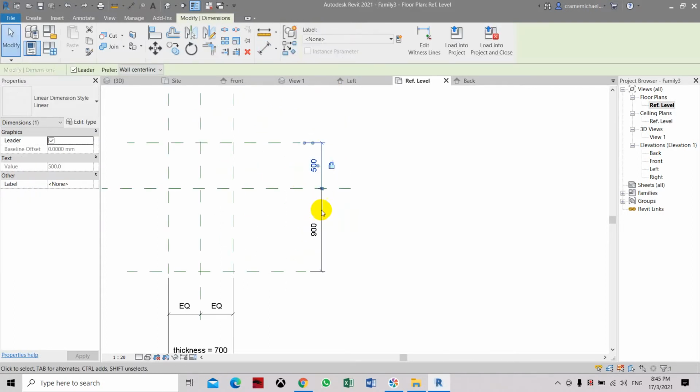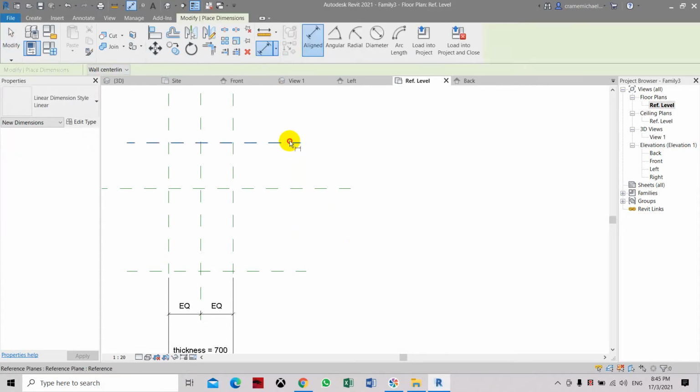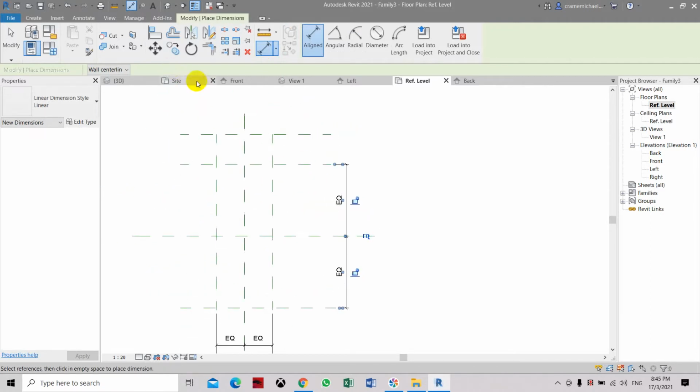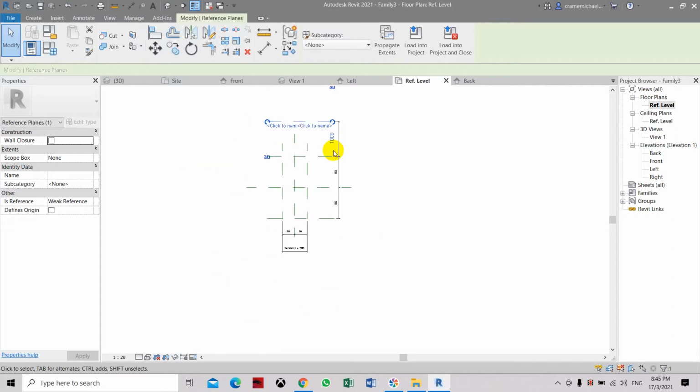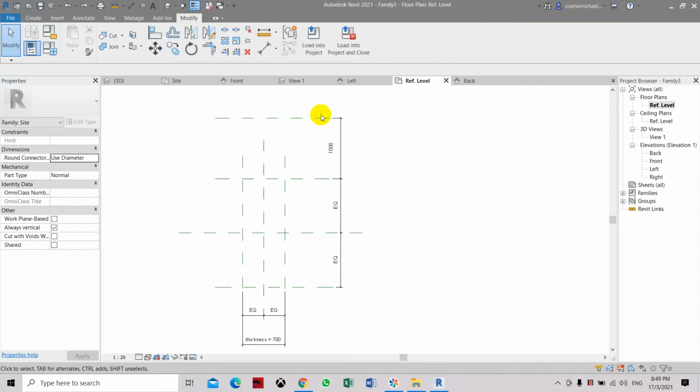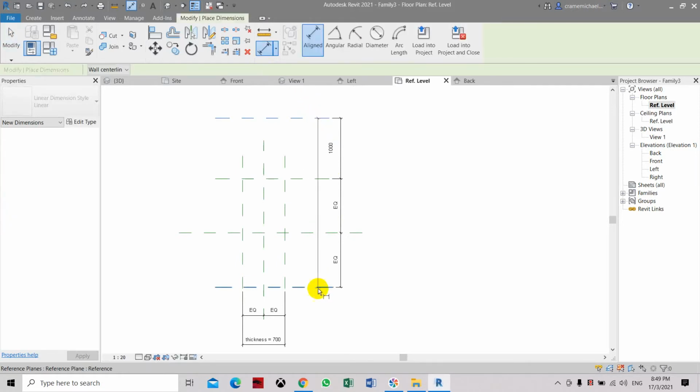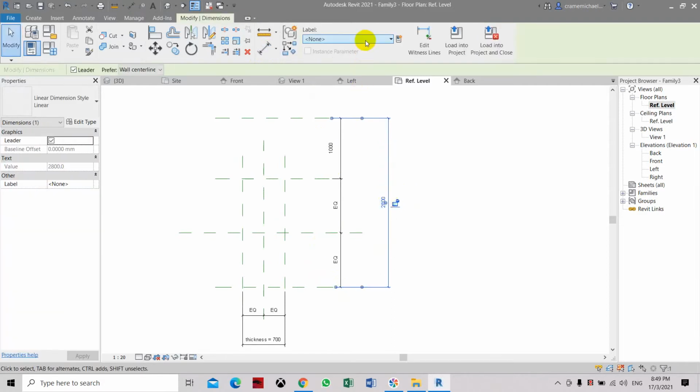Let's erase the dimensions on the reference plane. Dimension, let's set it equal. Then from here to here, let's set the dimension, let's say this will be around 1000. This is the arrowhead. Place the constraint for the length. So we need to define this now, and this is the overall length of the arrow. We have already created the parameter length.